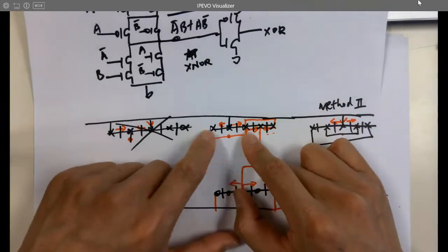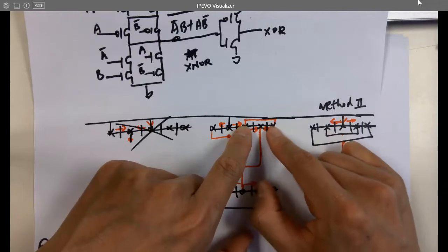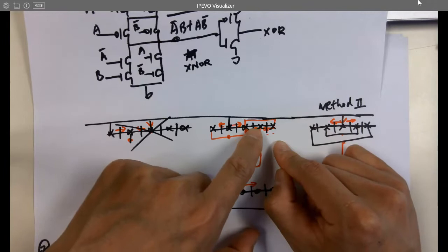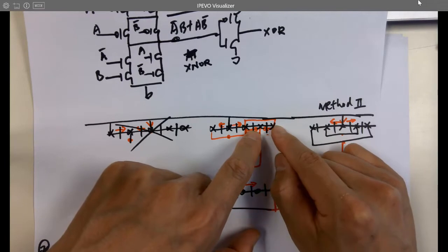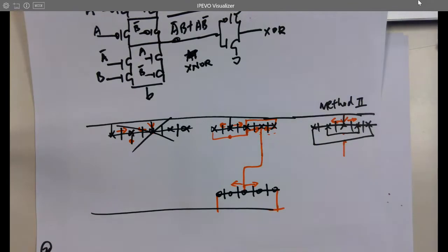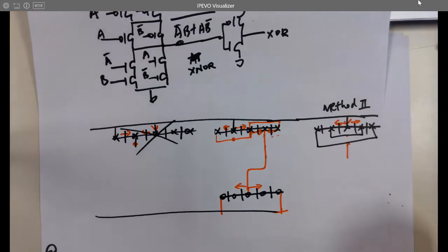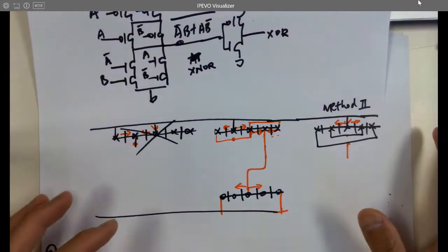Unless you are running this circuit at like 4 gigahertz or something, there might be a little difference, because this split into two, right? And then I think you need a trace to connect to this one and then get a parallel PMOS, but this one directly enters the PMOS here. So this takes longer time. If you have a little bit timing difference, there might be a little glitch in the signal. So if we have two equivalent circuits, we should favor the one that's more symmetric, I think so, yeah. But based on the speed we are running for the circuits, they are usually like kilohertz. You won't be able to see any difference.